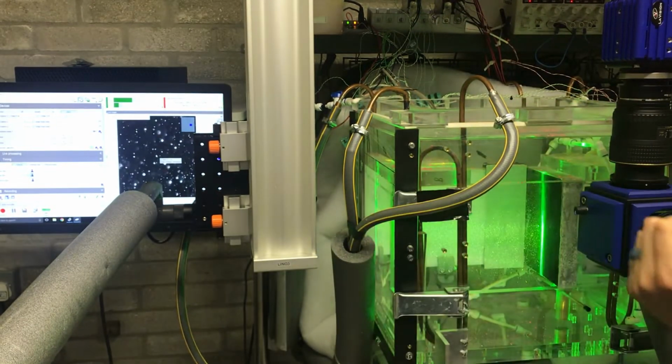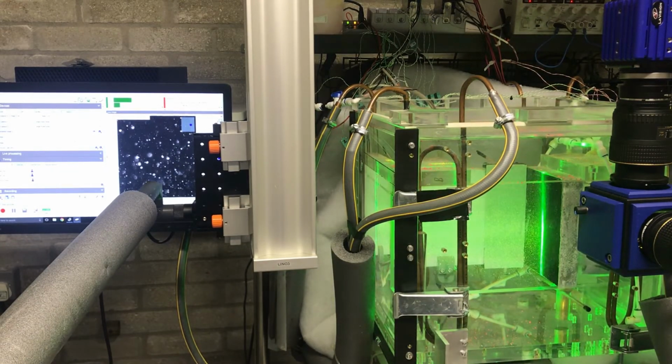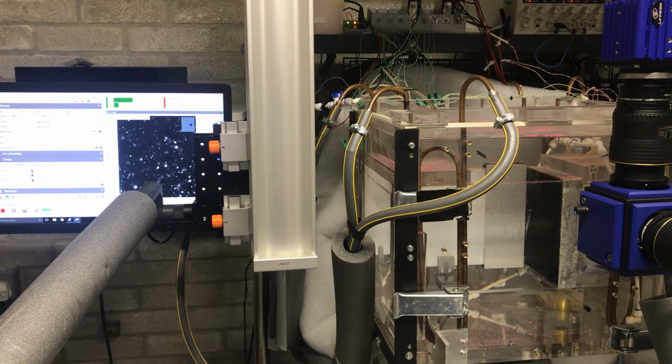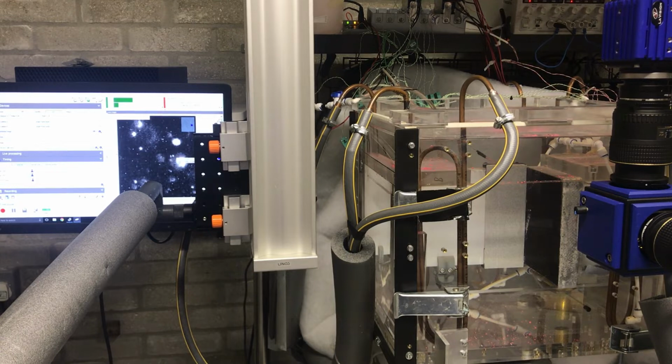Now what we're really looking for is for the particles to take up a certain size. It's a little bit difficult to do this when we have all of this information, all of this image, live. So if we take a single image now, okay, we've got a single image, we can now zoom in and see how many pixels these particles are occupying. And we've got a minimum requirement here. We want them to take up at least 3 by 3 pixels. Bigger is okay, smaller is not okay, because noise often occupies just a single pixel as well. So we want to have an obvious particle image.